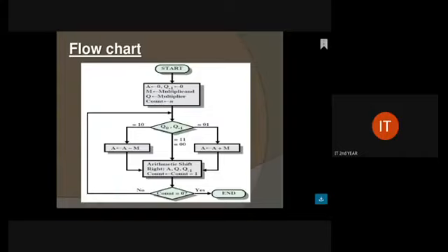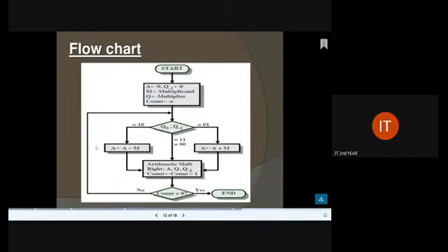Next we have to look into Q naught value and Q minus 1. Suppose when we are dealing with Q naught and Q minus 1, if the value is 1 0, then we will be moving on to assigning A tends to A minus multiplicand. If the value is 0 1, then we will move on to A tends to A plus multiplicand, that is accumulator plus multiplicand.